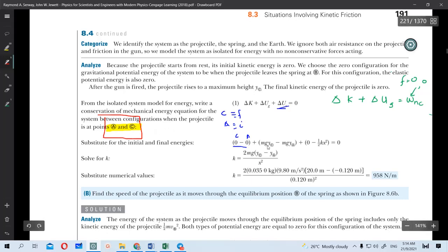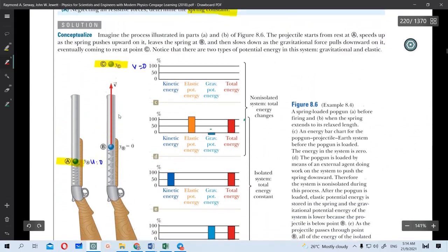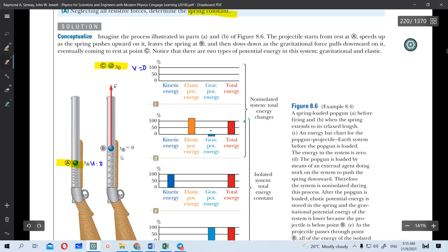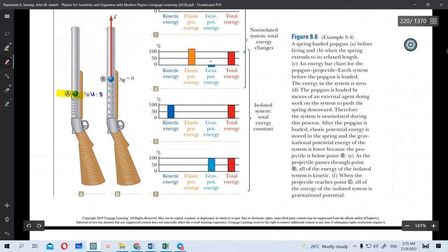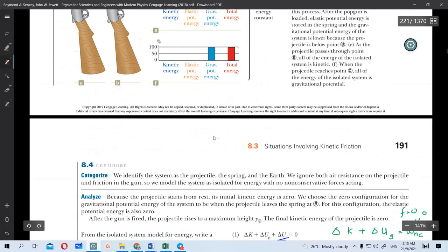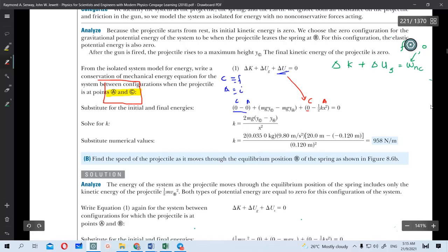Okay. And then, how about the change in the potential energy belonging to the spring? So we look at the positioning between C, as before, and the initial at A. Okay, now let's see why C is 0. Because at C there is no spring compression. The spring is fully extended, meaning at equilibrium. Compression is no longer occurring. So that's the reason why it's 0. But how about at A? So we notice that at A, yes, we have compressed it. And then you might get confused: should I include the negative or not?